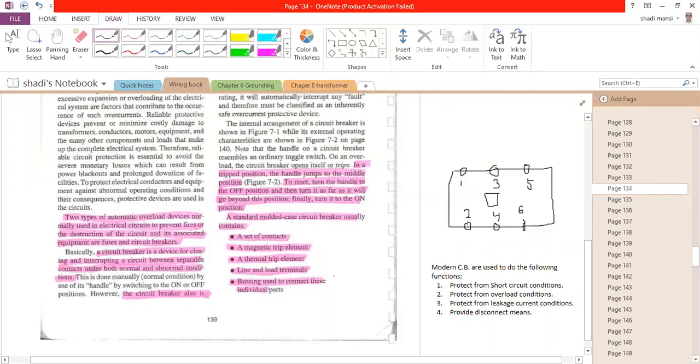It is very important because some electricians I have faced in my life, when we are talking about a circuit breaker, said, okay, whatever the input, whatever the output. No, we have to decide where the input and the output are. The odd terminals, 1, 3, and 5, are to be connected to the power supply. The even terminals are to be connected to the load, okay?